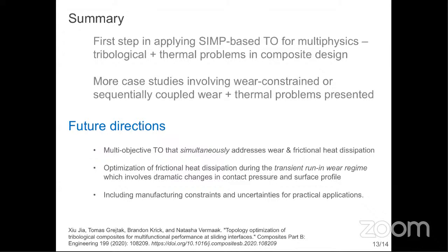We started with thermal optimization with a wear constraint. We also did sequentially coupled wear and thermal optimization, but there's plenty more work to do for the future in simultaneously optimizing wear and frictional heat dissipation. We'd also like to focus on the transient run-in wear, where there's more dramatic material loss, changes in contact pressure, surface profile, and of course, add manufacturing constraints.